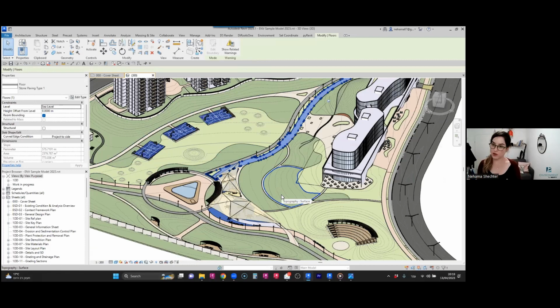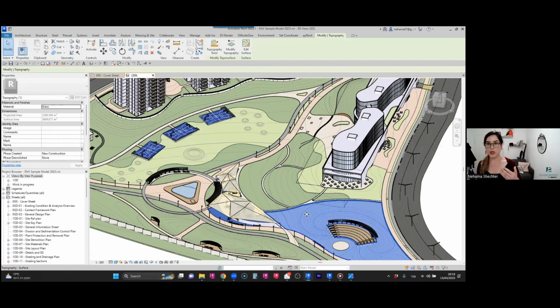Revit has a great feature called schedules that just allows you to take a parameter, put it in an Excel table, and in every stage of your project, you're able to know how much earthwork you have in your projects. Of course, assuming you modeled your existing ground, which is really easy if you have a survey.